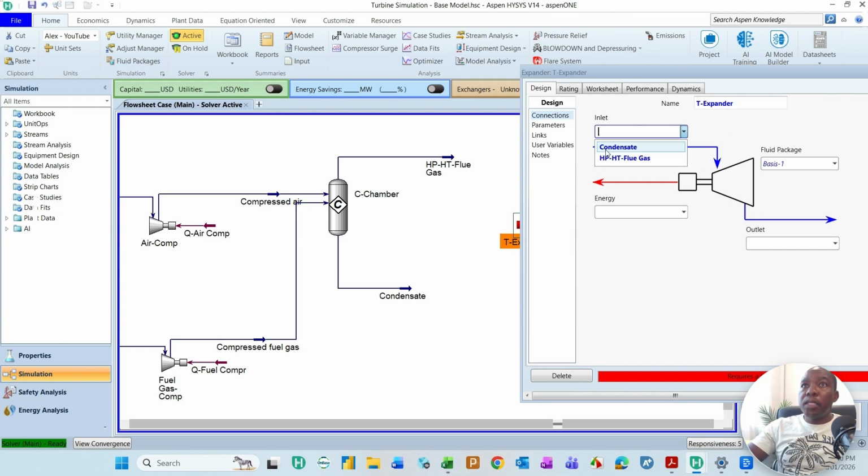And what's going in is the high pressure, high temperature flue gas. What goes out is the hot, I'll call this hot flue gas. The reason I just call it hot flue gas is now it has dissipated most, if not all, of that high pressure. So it expands and cools at the same time to liberate all that energy in the gas to drive this turbine. Q of the turbine, I'll call it Q turbine. So this is the power that the turbine produces.